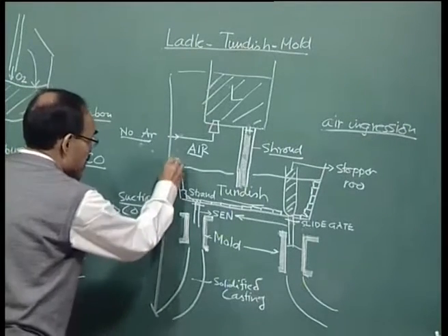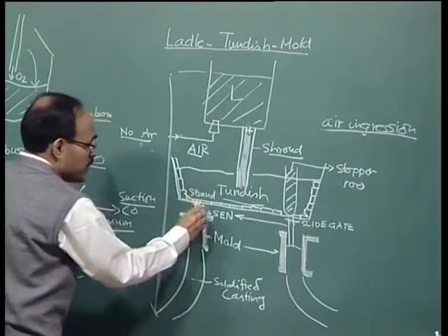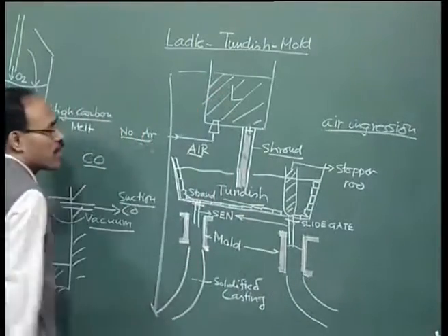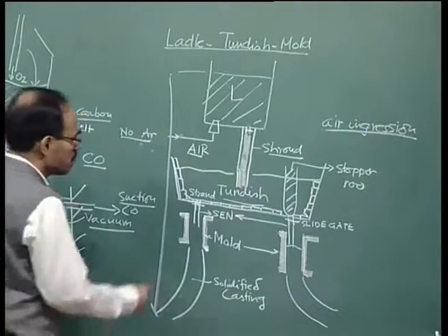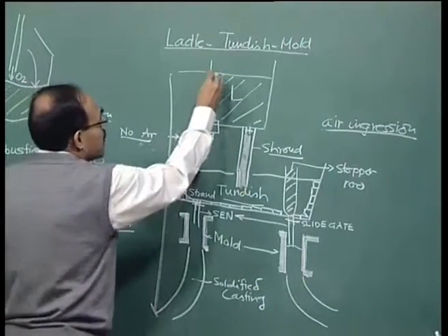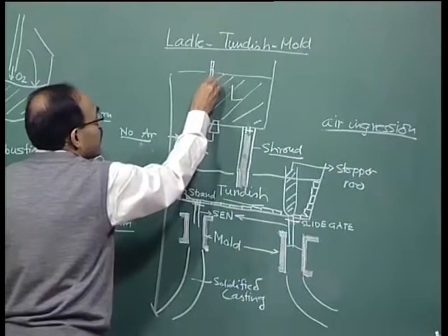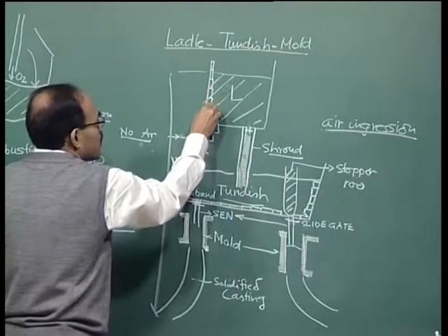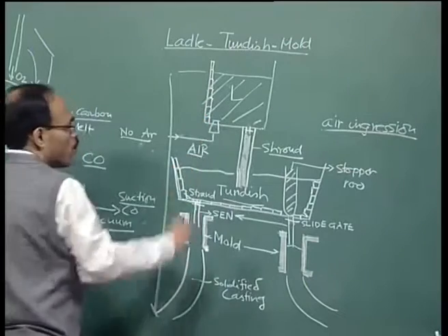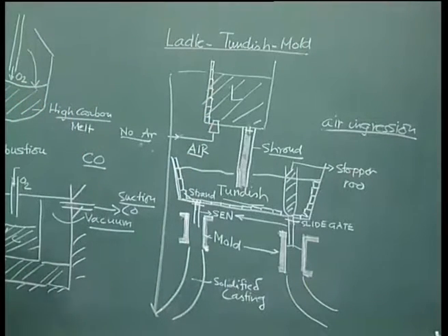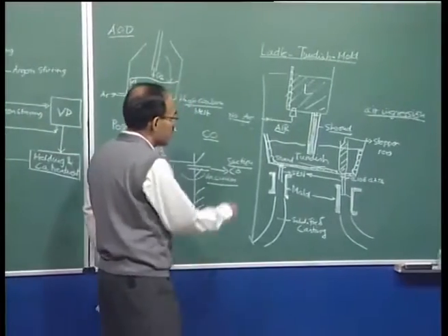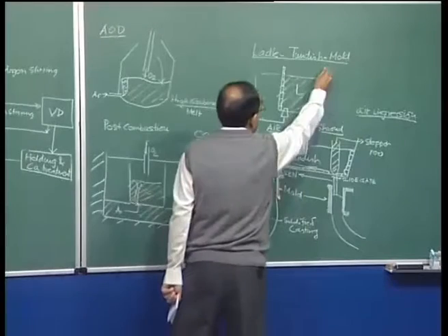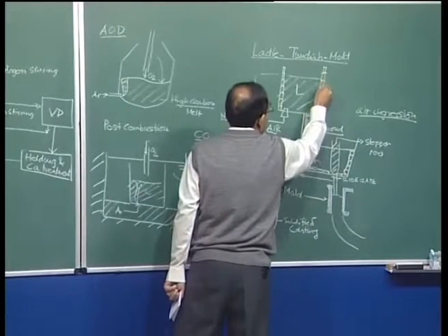is made. So, it is a steel lined vessel. Basically, the same type of refractories which are there in ladles are used, and the thickness of the lining is also almost the same as the thickness of lining in the ladle. So, there is not much difference. Holding and transfer vessels have similar types of characteristics. Magnesia bricks, basically magnesia tar dolomite lined bricks, are used in ladles and tun dishes.